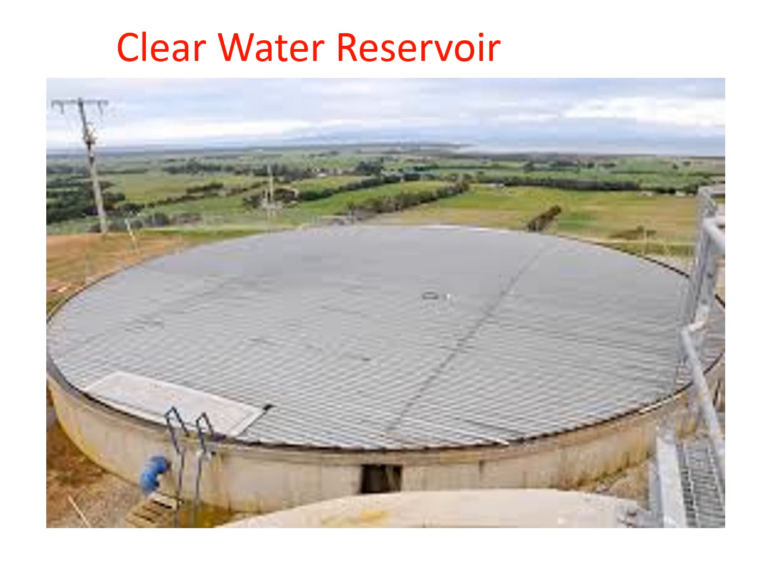So after chlorination, generally chlorination is done in this particular unit itself. Here this is the figure of the clear water reservoir, and it will store clear water. Generally inverted pipes of this shape are provided here, so that natural ventilation would take place, and they are bent so that birds or some impurities should not enter your water. That's why a bend is provided.